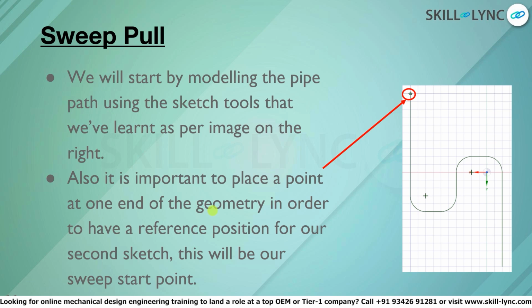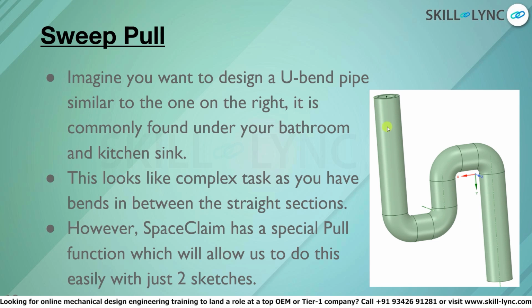You have pretty much the sweep or the curve that the pipe follows and the cross section. If we know these 2 pieces of information or these 2 items of the sketch, then we could combine them into this 3D model over here with a sweep action. So in essence, what the sweep tool will do is pull, as we have done similarly on different areas of the sketch. It will pull that area of the sketch, but it can follow the trajectory of a predefined curve, which we will define right now.